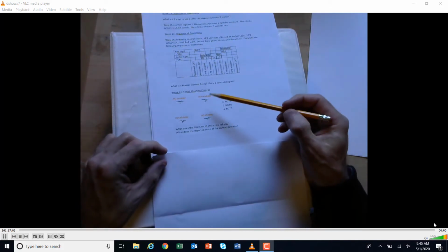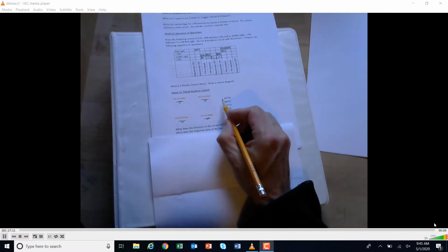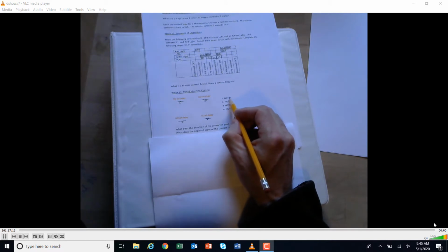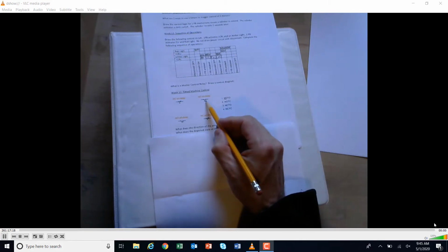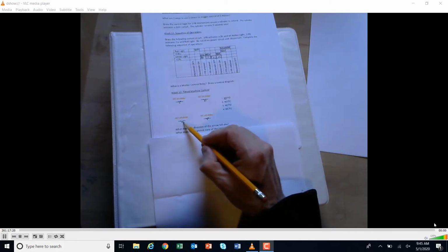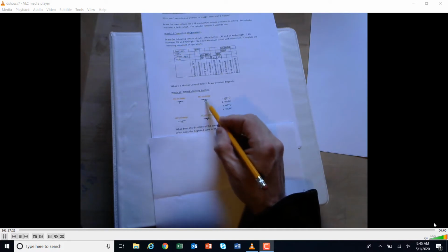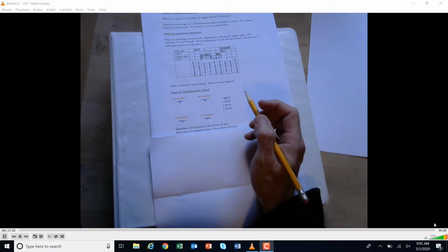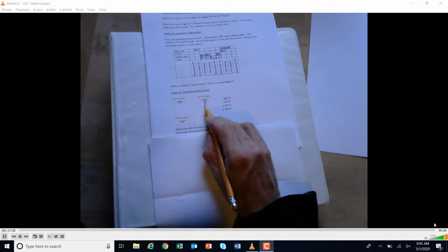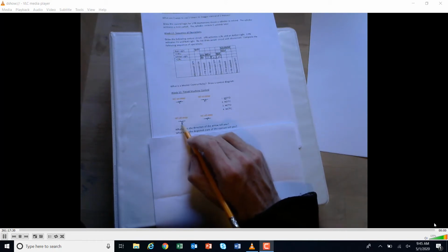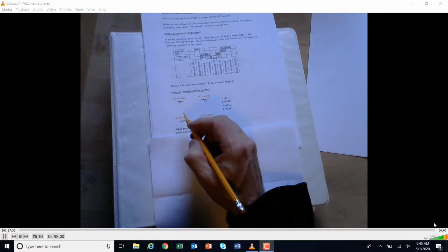So we have our timer machine control. We went over the contacts here of how they worked, which ones are on delay, which ones are off delay. And just to remember, a normally open, timed open. So we start with the way that it's drawn, normally open. Well, this one's drawn open, and this one's drawn open. So it's one of these two. And then it's going to time to open. Well, this arrow is indicating to close, and this arrow indicating down would be to open. So this is going to be number 1.